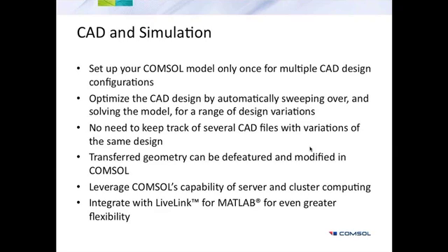So you still have the possibility to bring something over with the interface and then modify it inside COMSOL. And again, the LiveLink interface integrates into the same environment that contains the whole of COMSOL Multiphysics, so you can leverage all the other possibilities of cluster and server connections and computing. You can integrate it with LiveLink for MATLAB for scripting capabilities as well.